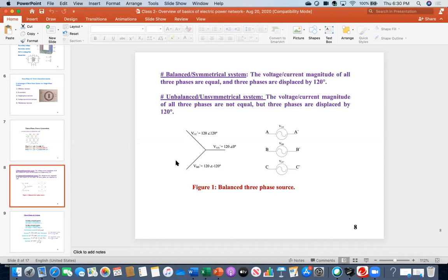And what is the consequence of current flowing? I square R, there will be some loss. And what is the effect of the loss? Loss means there may be some heating. The system will be less efficient. And then what might happen? For example, you are a personnel standing between phase A and phase B. One has 120 volts, the other has 100 volts. Current will start flowing. If you are barefooted, you might get shock. Do you understand?